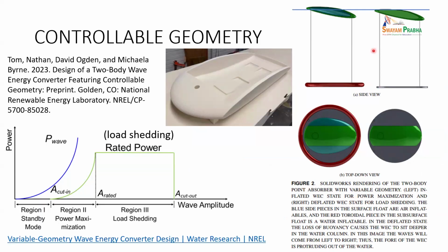So this is a buoy, and this is the still water line. You see this line, and if this buoy has a cross section like this one, you pump air in, then it floats up, right? When it floats up, here you pump this tube, pump water in, make it heavier. So basically, for the floater, you can change the geometry, especially the water line. What's that water line?